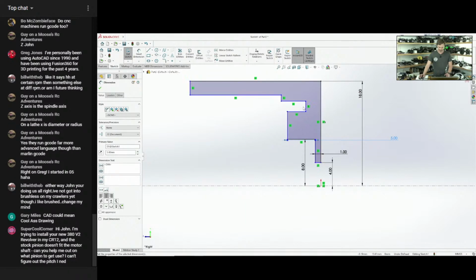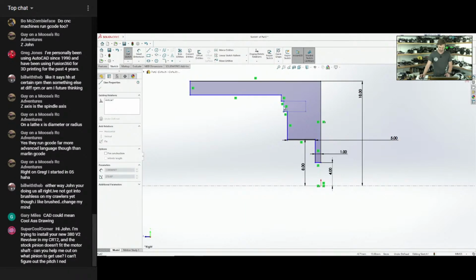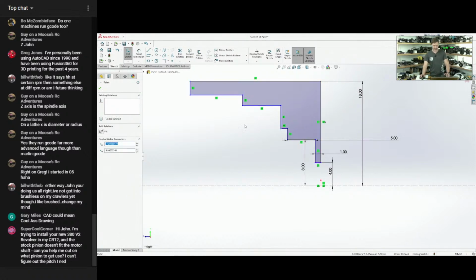I'm sure there's got to be somebody out there that does. All right, we're going to turn that smart dimension off. I need to pull this out just a little bit. All right, so we've got a 5 millimeter depth of this bearing pocket. We have a 16 millimeter, 8 millimeter radius from our center line on this pocket. Then what we will need is some steps for the stator and some steps to make sure that we don't have wires from the stator crashing in.